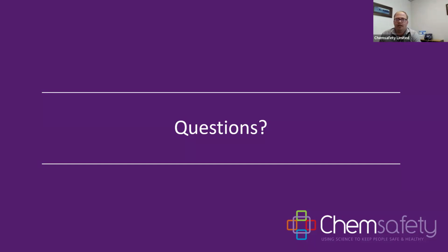I've got another question here. Where work is periodic, e.g. a worker may only be exposed for 2 hours in a workday in a dusty environment, arranging fit testing is not practical. Is a negative or positive pressure test sufficient where the exposure to the material is not highly toxic? With the standard, if you're having to wear a respirator, you would need to get fit tested just once a year, or when the situation changes.